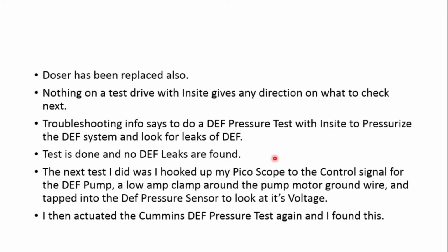So, after the test drive, I went back and I looked at the troubleshooting info, and it says you do a DEF pressure test with Insight to pressurize the DEF system and look for leaks of DEF. I'm like, okay, yeah, that's a good test. So I did that test, and I couldn't find any leaks. There were no leaks whatsoever.